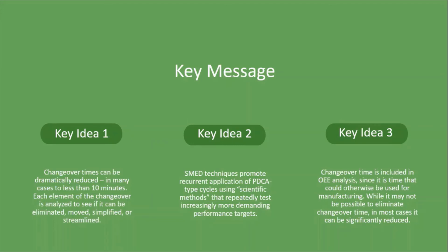SMED techniques promote recurrent applications of the PDCA type cycles using scientific methods that repeatedly test increasingly more demanding performance targets. And changeover time is included in OEE analysis since it is time that could otherwise be used for manufacturing. While it may not be possible to eliminate changeover time, in most cases it can be significantly reduced.